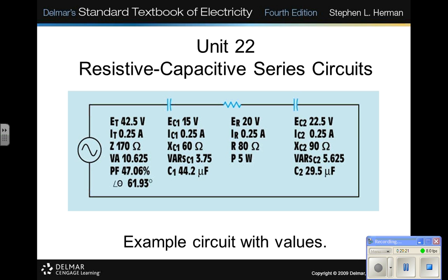Oh, we like that. Except now we have two capacitors in series, right? Now, how do capacitors in series add up? The exact opposite of the way we treat a resistor. A resistor in series, we would just add up, but a resistor in parallel, we add the reciprocal. So if we're going to add capacitance, we're going to add the reciprocals together, right? To get the reciprocal of the total. Everybody agree on that? Everybody understand what I'm saying? That's not just for the resistance.